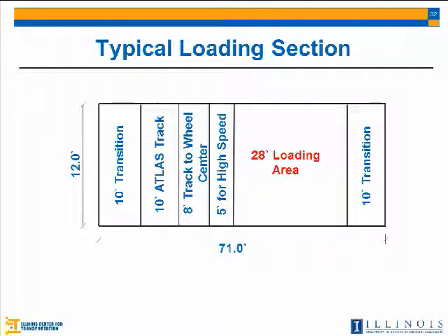So we need to look at those two variables, and hopefully I will look at them in more detail when I start doing my component tests, because I'm going to test the binder and the aggregates, and there will be a new concept now used a lot for moisture damage, which is looking at the surface free energy of both of those components. We try to come up with a new concept that can predict, even without doing all this hard laboratory testing, at the beginning that this binder and this aggregate can be mixed together and will work so well even with the existence of moisture.